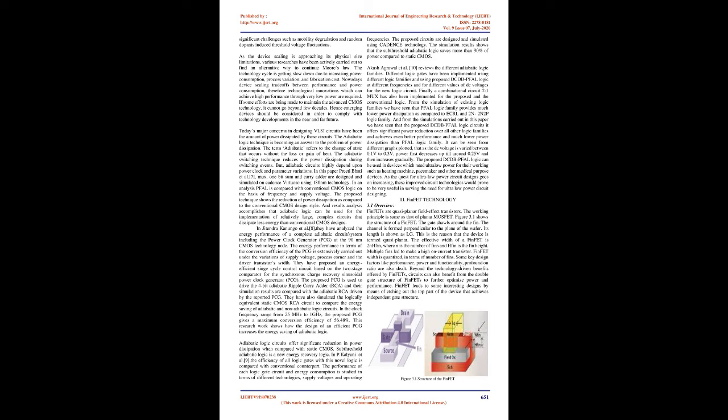New latches and flip-flops based on independent gate FinFETs are proposed in this paper. S. A. Tawfik et al. [3] aimed to simultaneously reduce the power consumption and the circuit area. With the proposed independently biased double-gate FinFET sequential circuits, the active power consumption, the clock power, the leakage power, and the circuit area are reduced by up to 47%, 32%, 42%, and 20%, respectively, while maintaining similar speed and data stability as compared to the standard sequential circuits with tied-gate FinFETs in a 32 nm FinFET technology.